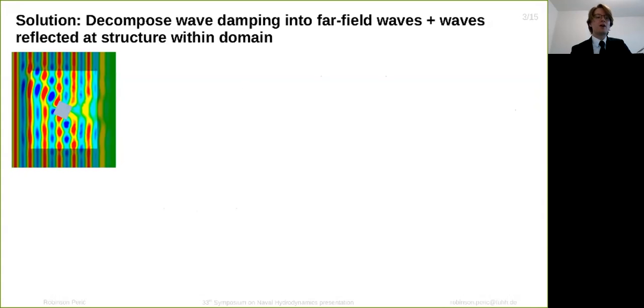And to look at the solution, let's look at how such a simulation might look. We have here a pontoon subjected to regular free surface waves. The pontoon is strongly wave reflecting, and it's shown in gray. And the forcing zones are attached near all vertical domain boundaries, shown here shaded gray. And we use different types of forcing here. For example, on the left-hand boundary where the waves are generated, we force towards the far-field wave solution to generate the desired waves and minimize wave reflections.